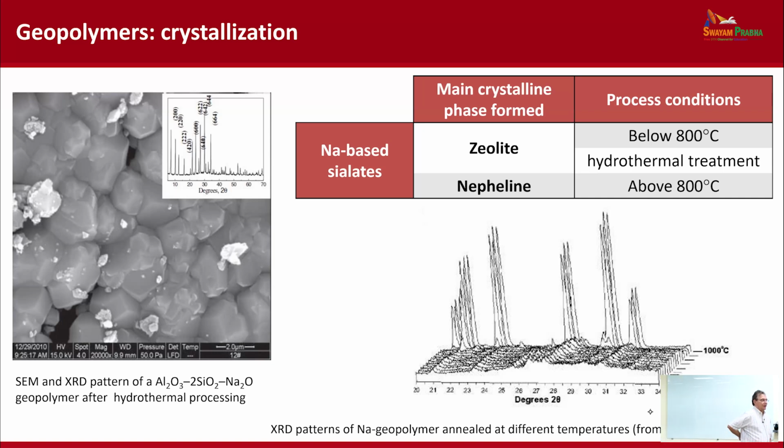Some people in China, for instance, use cesium-based materials. And in that case, you make a ceramic phase called pollucite that has a melting temperature of 1950, if I remember correctly. And the reason for doing this is that you have all the advantages of forming a component from a liquid, from a suspension, and consolidating at room temperature. So you don't need to sinter powders, okay?